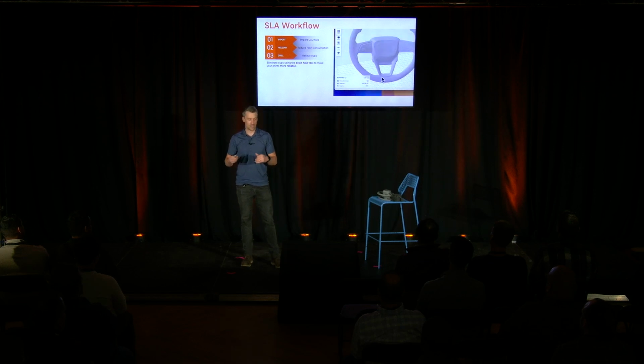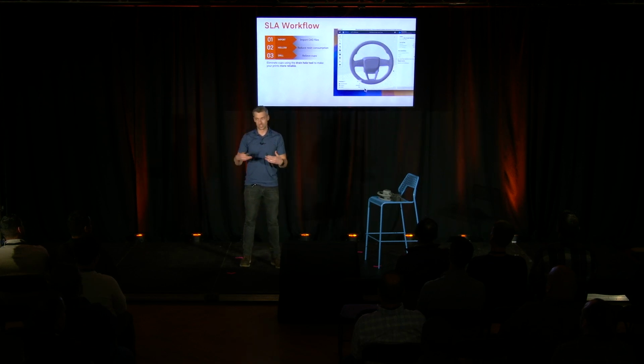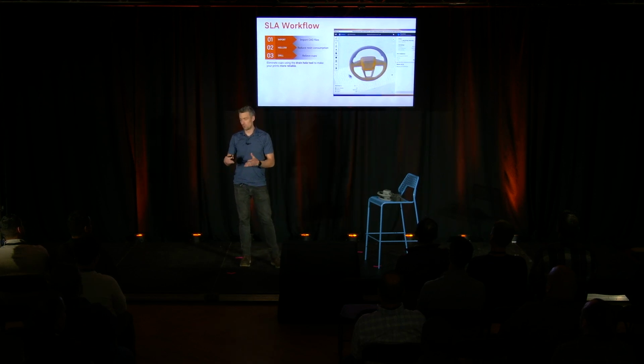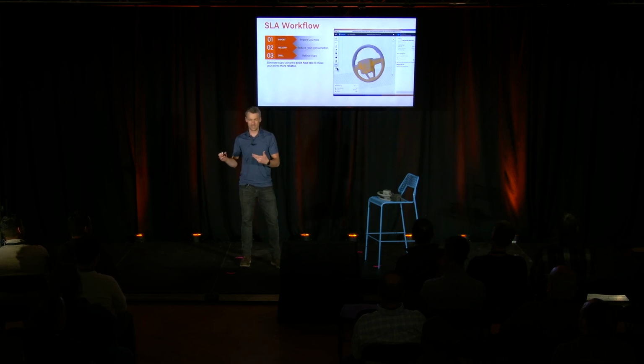Just as a side note, if you don't want to add drain holes, there's also the cup mitigation mode, which can be found in the print settings editor, which is a new feature we added, I think earlier this year, I would say, in probably Q1 or Q2. And the print settings editor allows you to edit some of those knobs. That's one of those options that you can turn on cup mitigation. It will slow your print down a little bit, but you'll be able to print with cups still. And in most cases, you'll have a pretty reliable outcome.